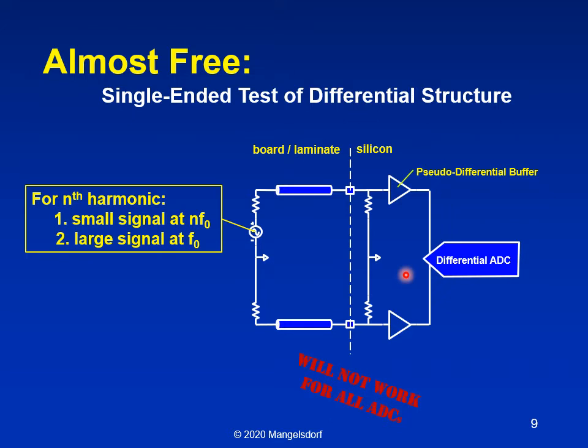Because in fact, when you drive a differential input with a single-ended source, you get a lot of common mode. And depending on the architecture of the input stage, that can be devastating. So this will not work with all ADCs, but I have used it for some. And when you do, it's quite powerful.